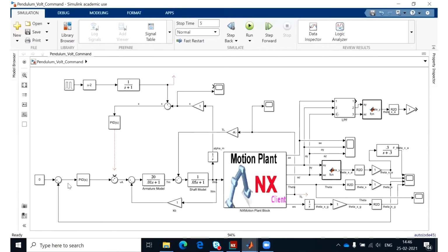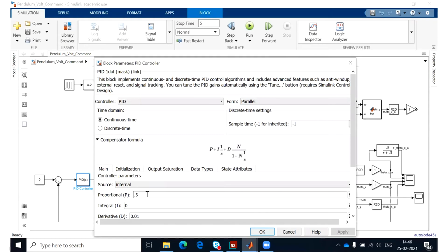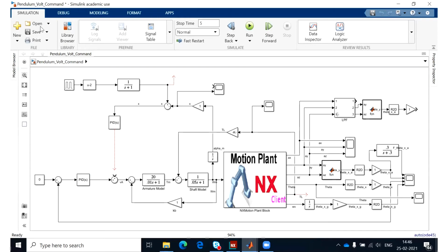And we can use a PID controller, but later you will see that you don't need an integral term here. A PD would be enough. You can use a PD controller to control the system. So I can select the value here. Let me select a high value for P. It depends, of course, on the parameters of the motor, but for now I select a P controller, and I show you how or where to check that.